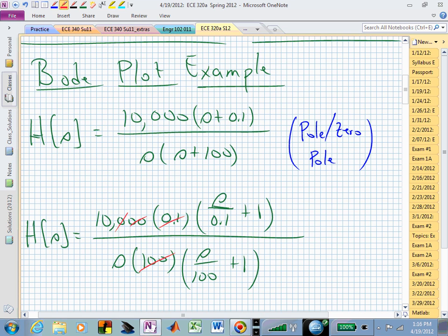If I ask you the opposite question, what's happening at low frequencies in the phase? You can say, oh, let me see if I have anything at the origin. He's trying to trick me here. Well, you do. You have a pole at the origin, and what does that do? That always contributes minus 90 degrees. Is that making sense? So you started at minus 90, you kind of come up, and then you go back to minus 90.